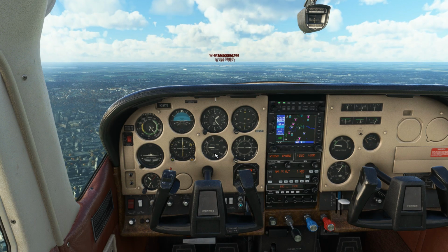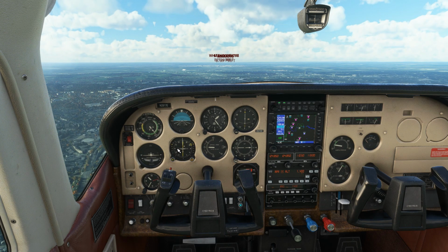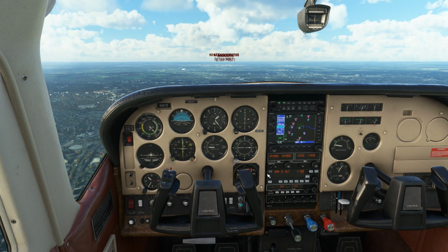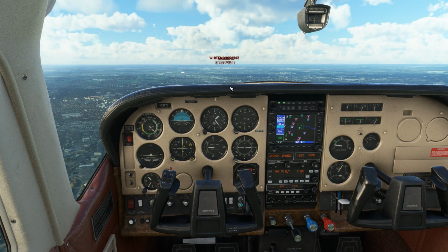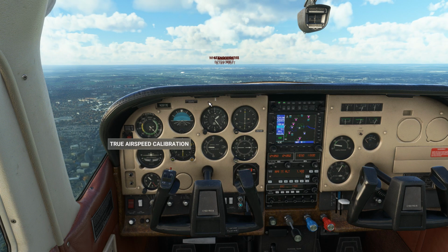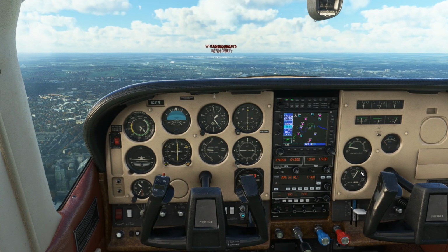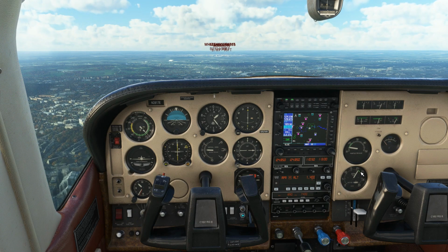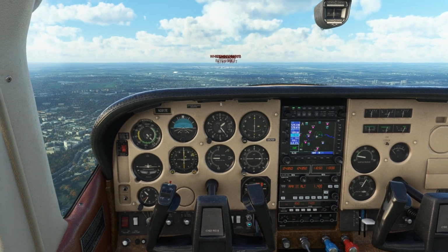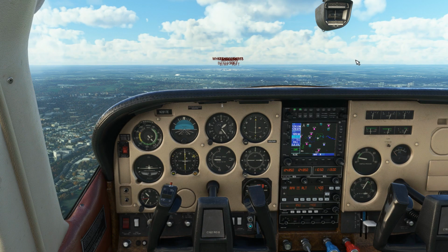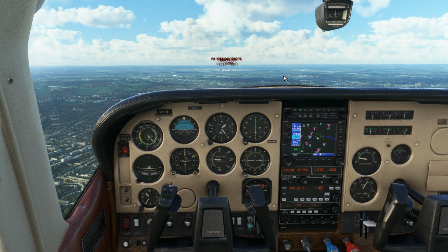And I want to do that, you want to do that before it starts descending under the glide. I mean, I could have waited till these indicators started moving down, but before these start moving down, because you've got it in approach mode, it will lock on and start following the glide path down, or glide slope down. You want to have your aircraft at a good speed. I can see the RPMs of the aircraft here. Seem to be in the green region there, which shows it in optimal range. It's all looking good. Still at 1,400. We've not started to descend yet, but I think these are moving down slightly, or they will in a minute.